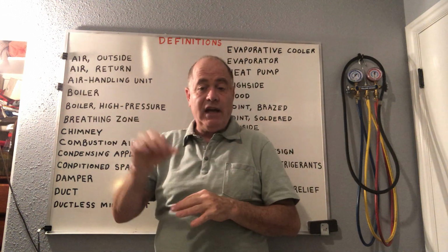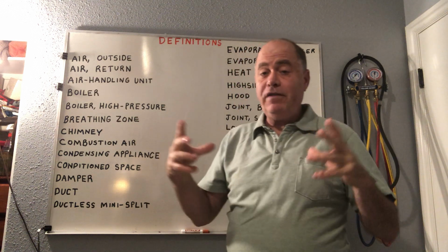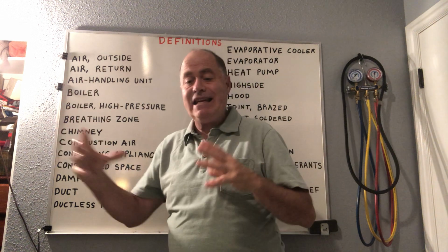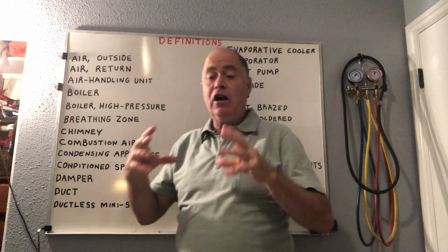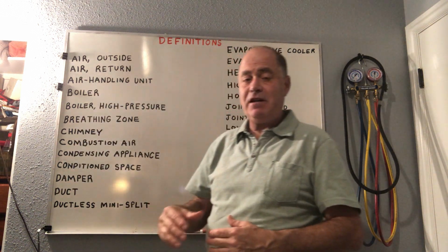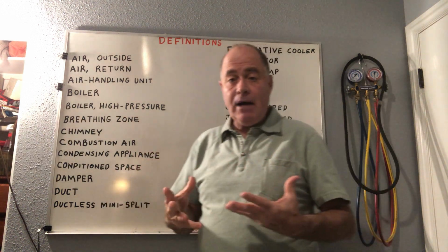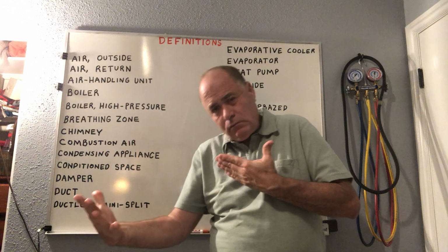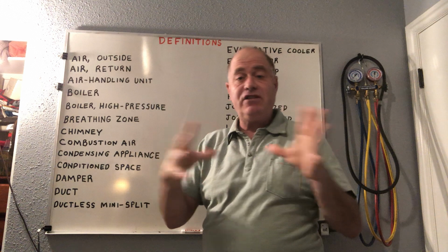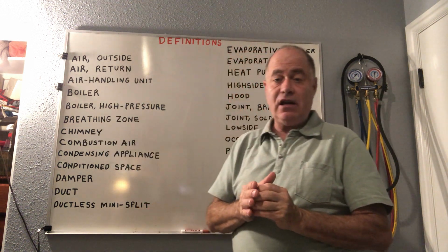Or the third way that you have a high pressure boiler is just water, may not be 250 degrees, may not be steam, but if you pressurize that water and heat it and raise the pressure up on the water to over 160 psi, that would be considered a high pressure boiler. And that's where, when you have a high pressure boiler, you need to have an operator, someone with a steam engineer's license, to be right there to take care of the boiler, to monitor it, because it is quite a bit more hazardous than a low pressure boiler,